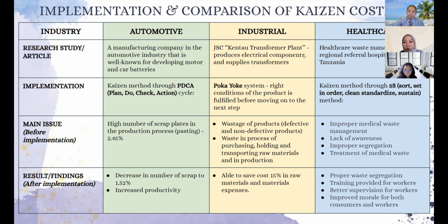The main issue occurring in the process of pasting is that the plates coming from the roll feeder fall into the grid 2 pieces simultaneously. It is supposed to be piece by piece and into the hopper, and therefore it creates a jam, which causes the plates to defect and be scrapped.